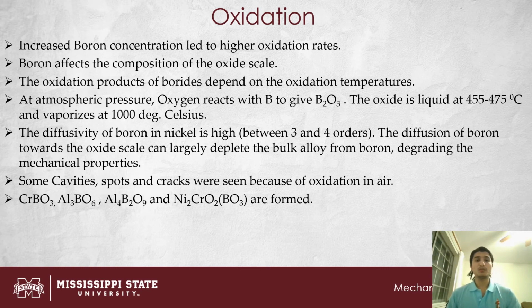The diffusivity of boron in nickel is very high, and the diffusion of boron towards the oxide scale can largely deplete the bulk alloy of boron, degrading the mechanical properties. Some cavities, spots, and cracks were seen because of oxidation in the air.